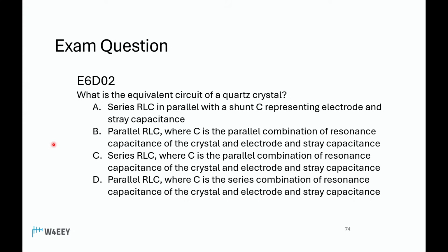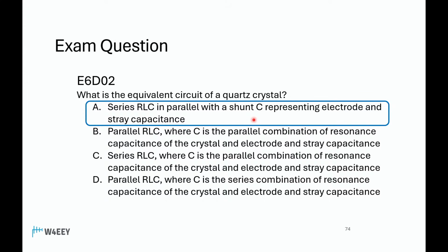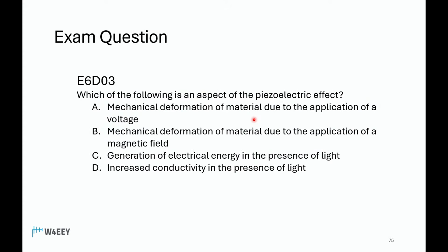What is the equivalent circuit of a quartz crystal? Bravo. Okay. Well, it is Alpha. Series RLC in parallel with a shunt capacitance representing electrode and stray capacitance. And there's a little shortcut to this one. It's the only answer that has the words shunt capacitor in the answer. Shunt C, it's called here. Which of the following is an aspect of the piezoelectric effect?